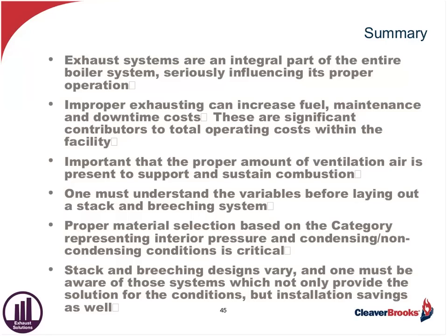Next question, when would a mechanical damper be added to an exhaust system? Well, we'd add the mechanical damper to control the gas flow, to give us the correct draft. If we have too much draft, we're going to want a mechanical damper to control the flow and the draft out of there.